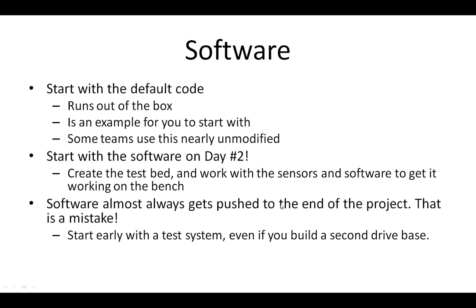In general, all three languages come with what we call default code. And the reality is that if you install the default code, put the joysticks in position, and hook the motors up according to the instructions in the software, up to PWM or motor control channels 1 and 2, for the main wheels, and if you hook it up in a certain way, you can actually get your robot driving around without even modifying the software. And there are actually a number of teams who do very, very little with the software.